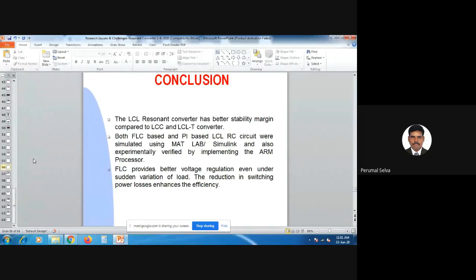At full load, an efficiency of 92.83% was obtained. As the load was decreased, efficiencies remained high. However, at 11% load, the efficiency of the circuit was measured as 79.9%. An added advantage of FLC is that with minor modifications, the same controller coding could be extended to control any type of DC to DC converter, since their behavior can also be described by a similar set of linguistic rules. Right. So next slide.